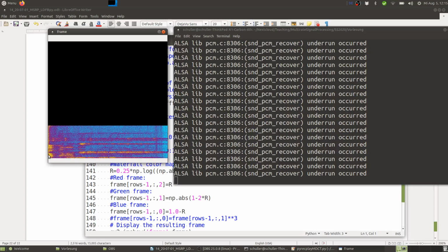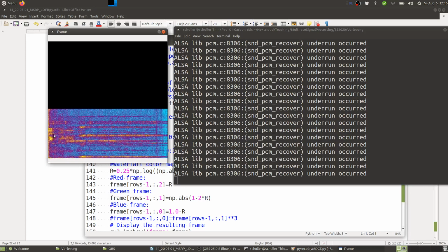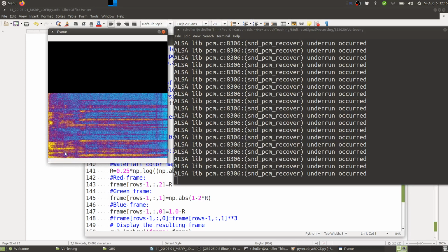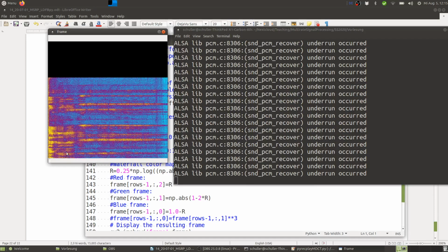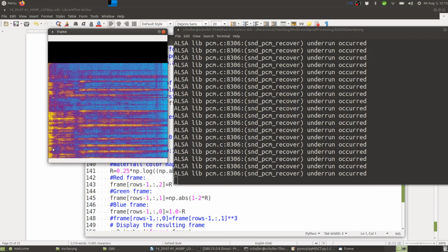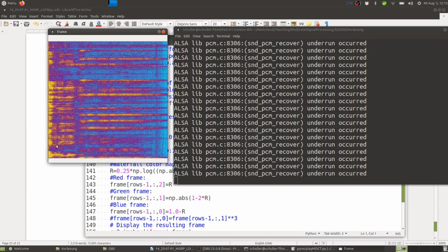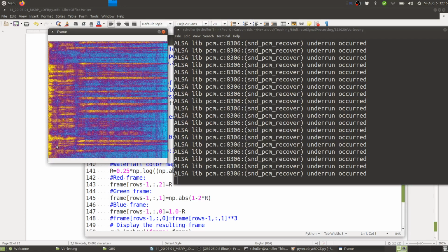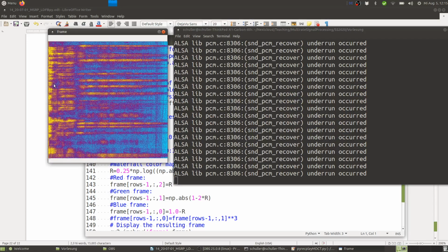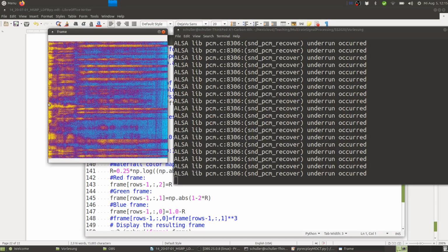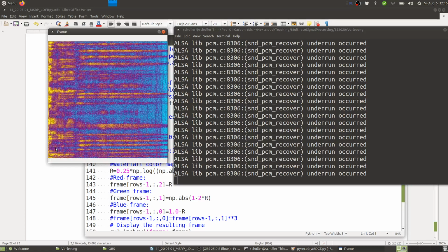On the left hand side we have the low frequencies, and you see indeed we get a nice resolution of our frequencies. So 512 subbands for the MDCT, and remember the MDCT has quite sharp filters, and that's why we get pretty good resolution here at the low frequencies of my speech.